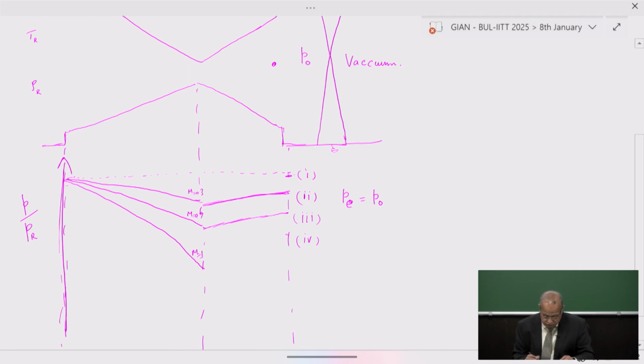Once it reaches M equal to 1 at the throat, there are two possible solutions as it passes through the divergent section. Either it can have a subsonic solution, or it can have a supersonic solution. Whether it will have a subsonic or supersonic solution will depend on the exit pressure. Now, if the exit pressure is higher, then we will have a subsonic solution here.